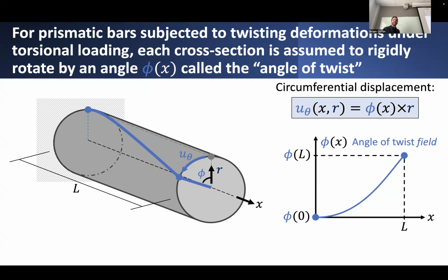We're still going to say that these plane sections, at least for the purposes of this initial analysis, and with a focus precisely on just axisymmetric cross sections like a circular bar, we can invoke this assumption and say that the plane sections of this kind of torsional shaft, this circular bar, are going to stay planar after deformation.